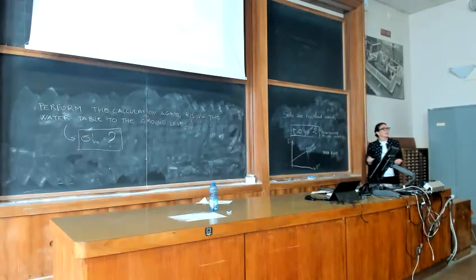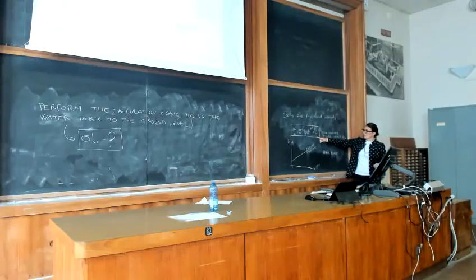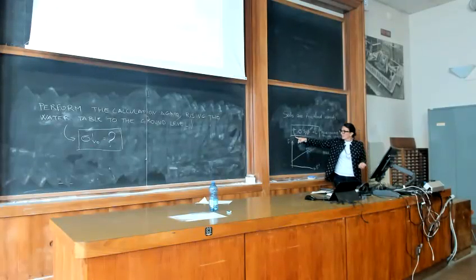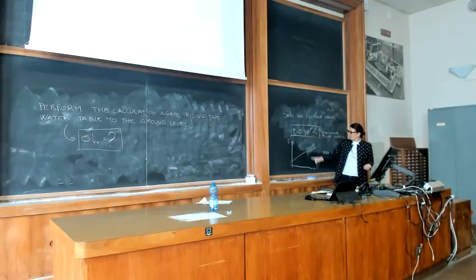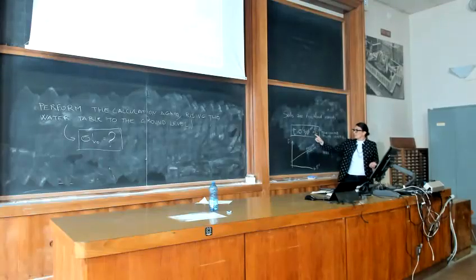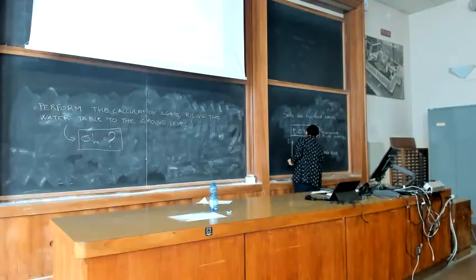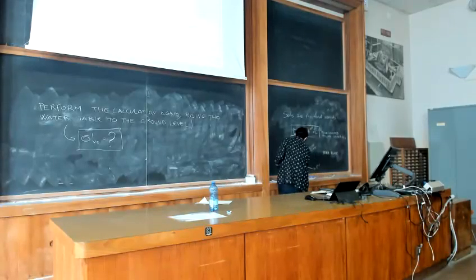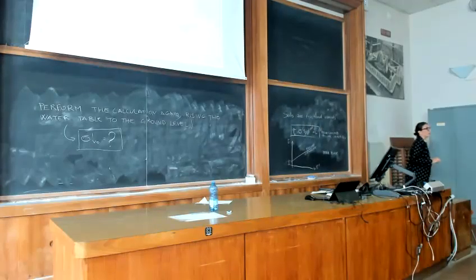So you can immediately see that in this plane, where tau is our y-axis and sigma is our x-axis, this equation defines a line whose inclination is phi dash and the intercept is c dash. This is the classical failure envelope that we consider for the soil and that we define through laboratory tests. Direct shear tests and triaxial tests are meant to define c dash and phi dash.